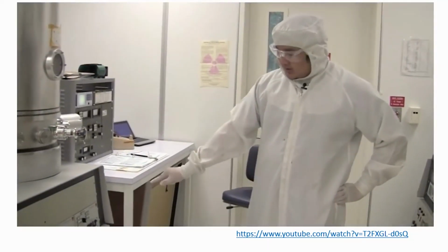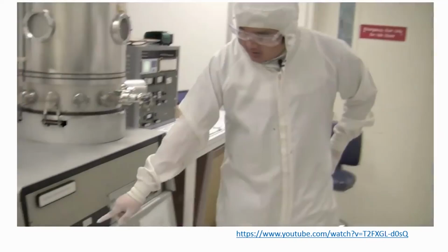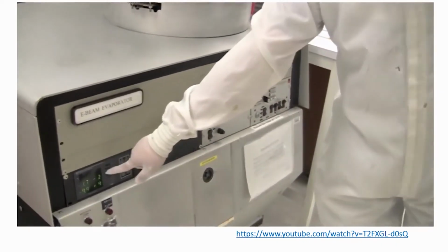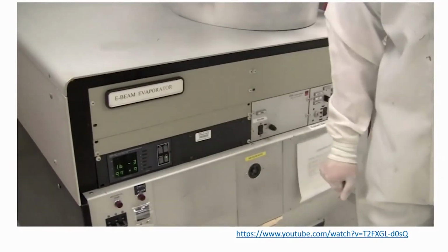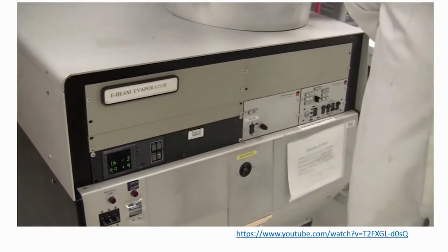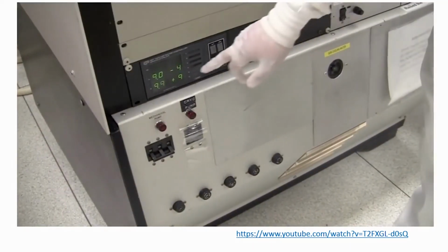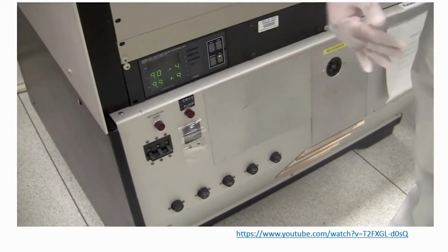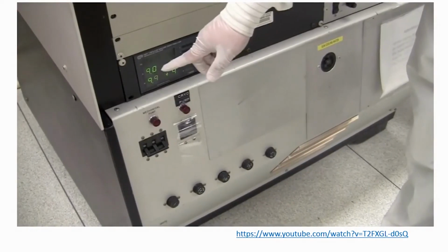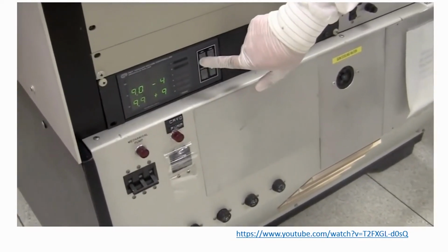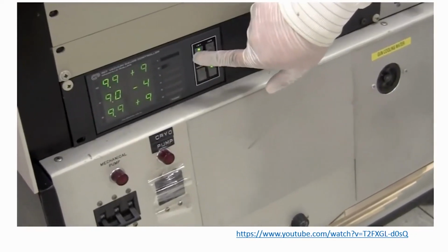So we're going to wait till the high vac goes in the -4 range. And when it goes in the -4 range, we're going to turn the ion gauge on. So we'll just wait for the high vac to pump down. Once the pressure of the thermocouple has reached its maximum scale, so we can't go any lower, we turn the ion gauge on, which is actually measuring the true pressure, because this is meant for low pressure measurements.